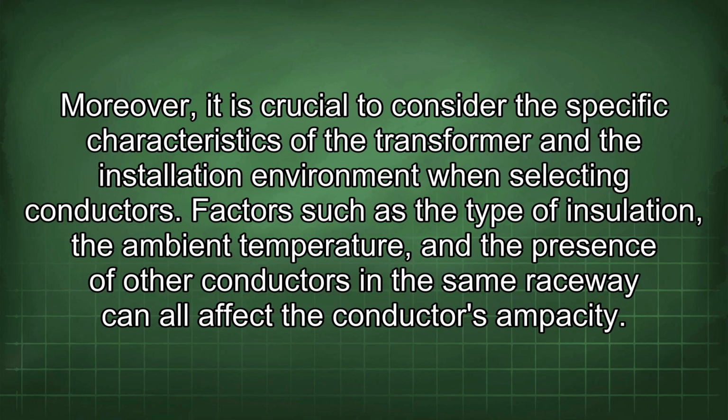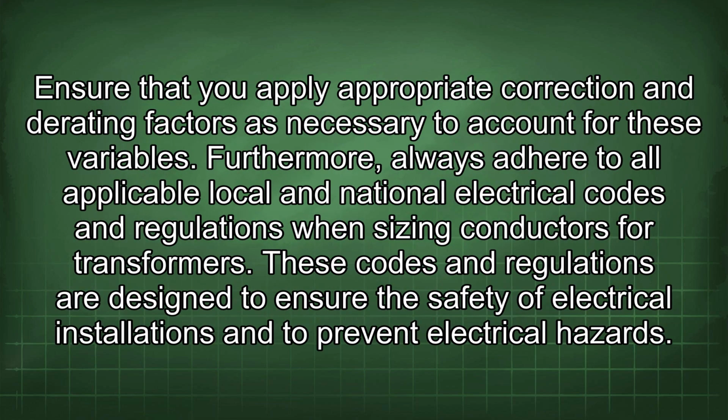Factors such as the type of insulation, the ambient temperature, and the presence of other conductors in the same raceway can all affect the conductor's ampacity. Ensure that you apply appropriate correction and derating factors as necessary to account for these variables. Furthermore, always adhere to all applicable local and national electrical codes and regulations when sizing conductors for transformers. These codes and regulations are designed to ensure the safety of electrical installations and to prevent electrical hazards.